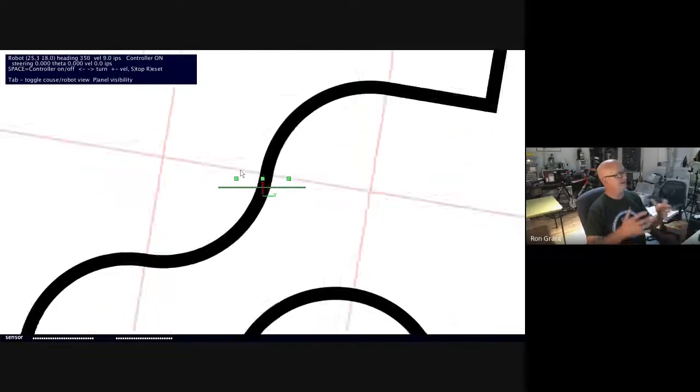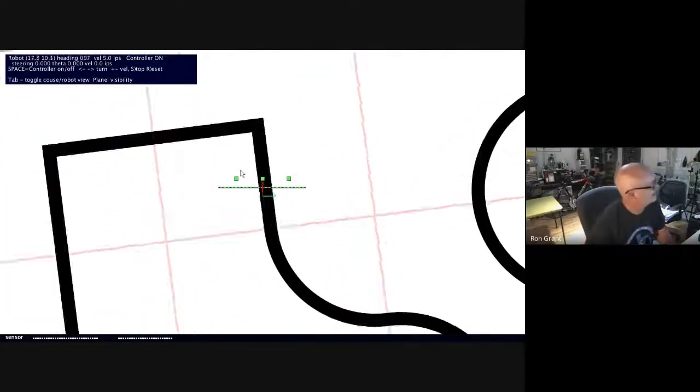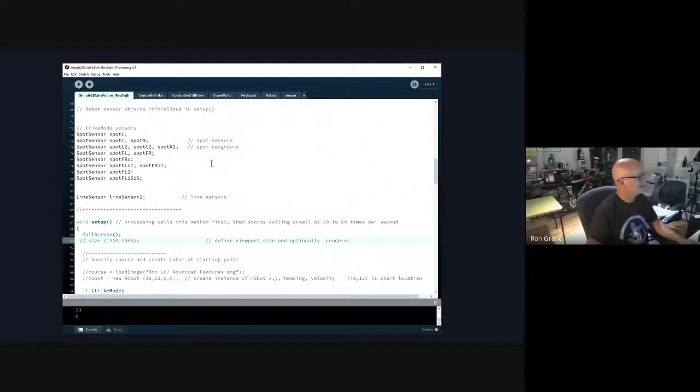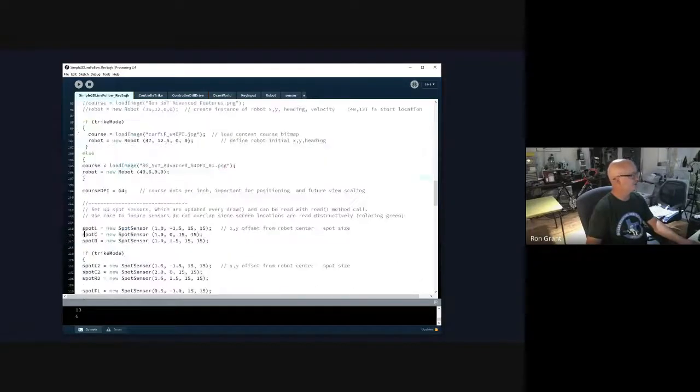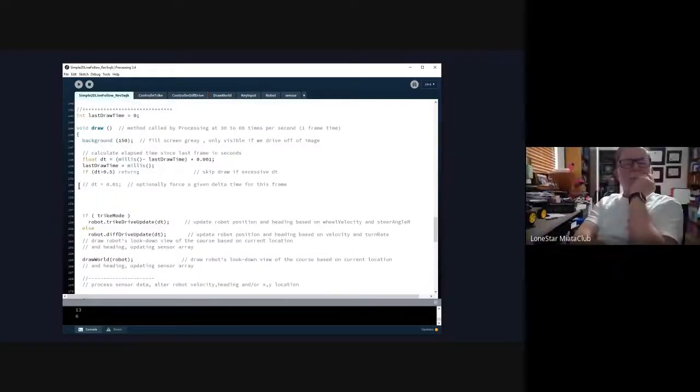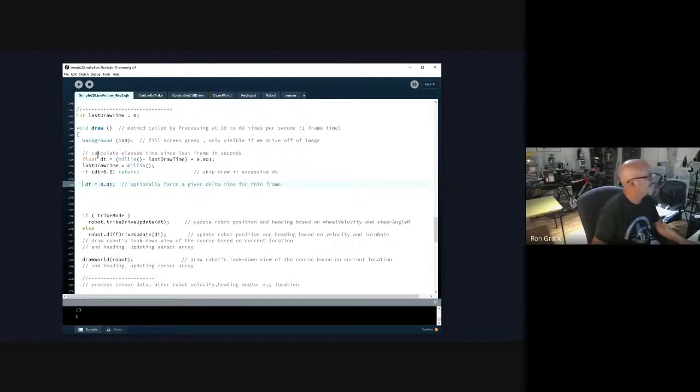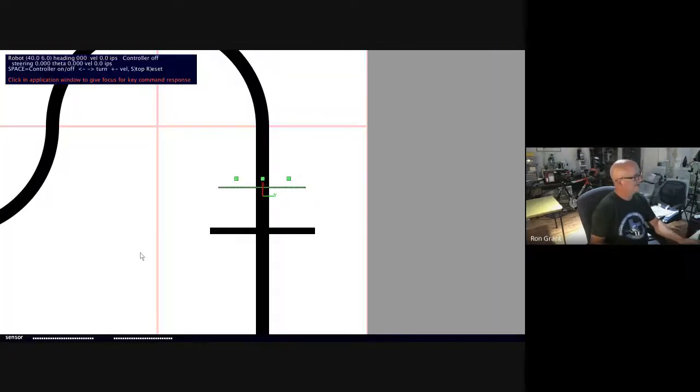In this case, that's sort of an example of if we didn't have a very good graphics card and we were noticing the simulation was bogging, what I'd be inclined to do is fix this to a value. I'm going to make it a 50th of a second. It'll slow down the simulation, but it should be cleaner and less jumpy. Let's see what happens.